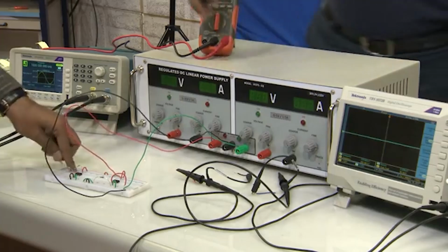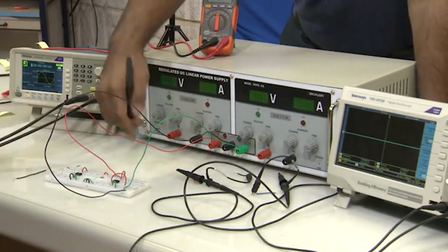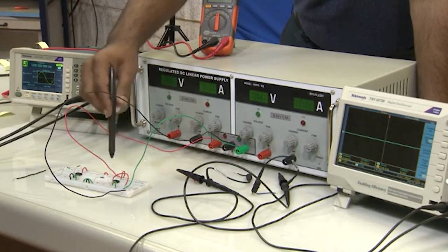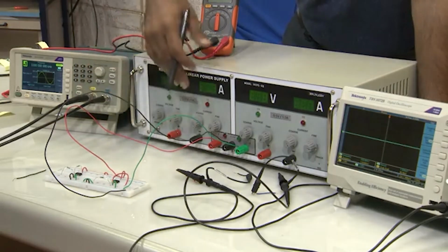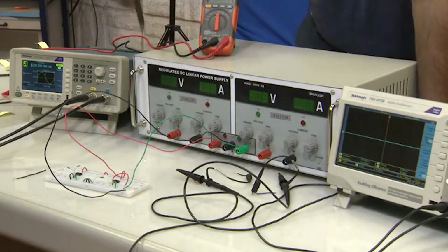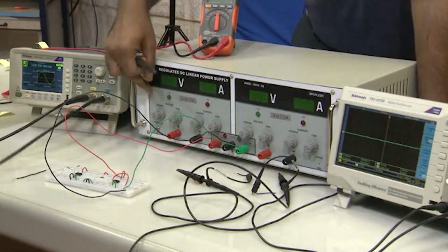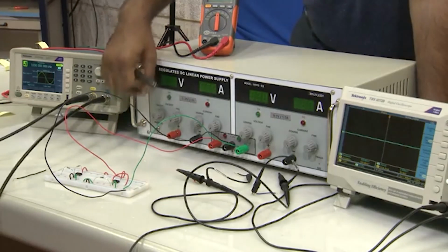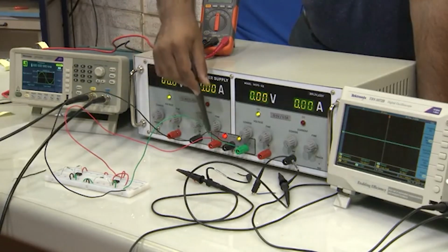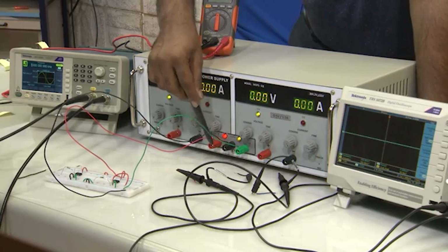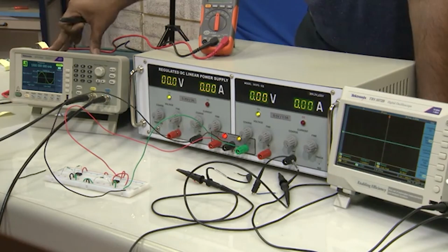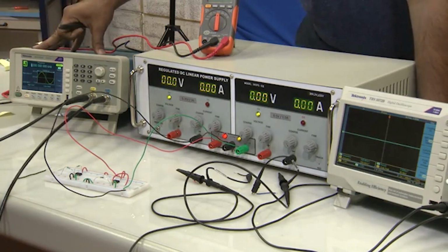So, we now have connected plus 15 and minus 15 to the non-inverting operational amplifier, that means pin number 4 and pin number 7 are connected with minus 15 and plus 15 respectively. Now, we will apply the input signal. Before that we have to start the operational amplifier. So, we can now apply the power, yes, DC voltage, excellent. Here it is plus 15, minus 15, in these three, red, black, green. Now, we will apply the input signal from the frequency generator. What is the frequency generator input signal? Can we focus on the frequency generator please?